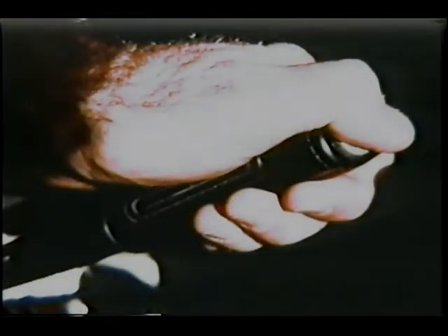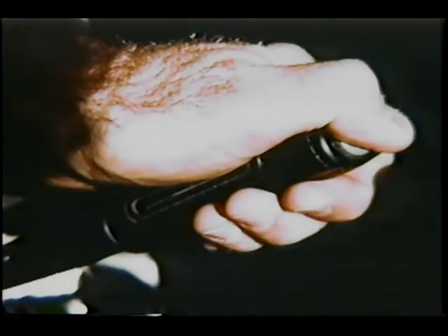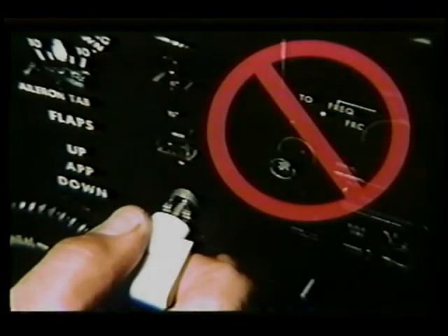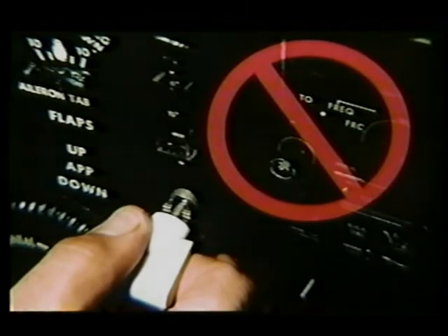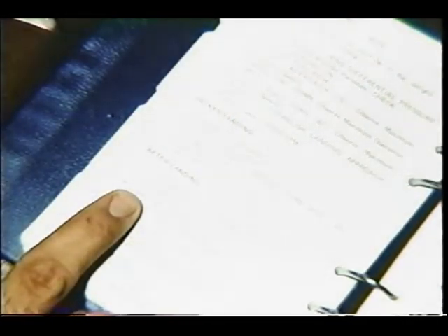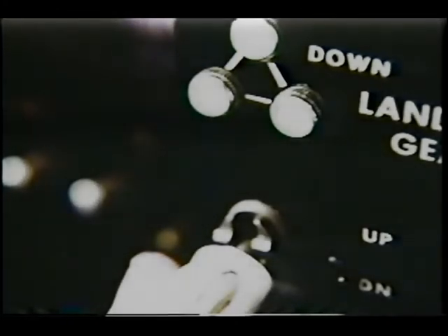First, some pilots' operating handbooks indicate that retracting the flaps will decrease lift, thereby putting more weight on the gear. It's really best, however, to wait on flap retraction until you're well clear of the runway so you can divert your attention to your checklist. Then you can concentrate on identifying the flap switch or handle properly, rather than taking the risk of retracting the gear by mistake. Look at it this way.